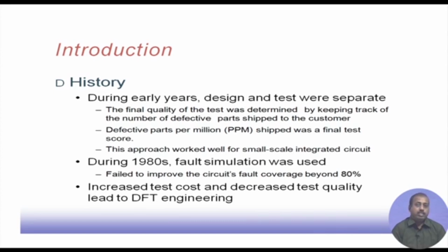For small scale design it is okay, because an SSI design has less than 10 gates or so, so it is easy, because the design is simple. In most cases we can design these test vectors, even if the test design has been done beforehand. Then came fault simulation. Fault simulation is, given the design and the test vectors, we try to see how many faults are getting covered.